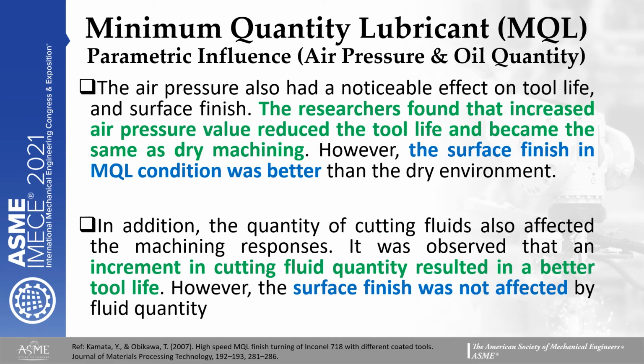Some other important MQL-based parameters are air pressure and oil quantity. The researchers found that increasing the air pressure value can reduce the tool life, and MQL technology was acting just like dry machining. However, it provided a better surface finish as compared to dry cutting.